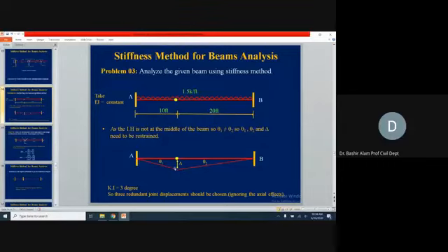At the bottom, if you come here now, this θ1 will be equal to this rotation, if you are following my cursor, and θ2 will be equal to this rotation now. Means at this hinge, we will be having two independent rotations now, θ1 and θ2, and those are becoming our unknowns now. So two displacements are 2 degrees of freedom because of this θ1 and θ2. And one is the vertical settlement now. So this vertical deflection will become our 3rd degree of freedom.